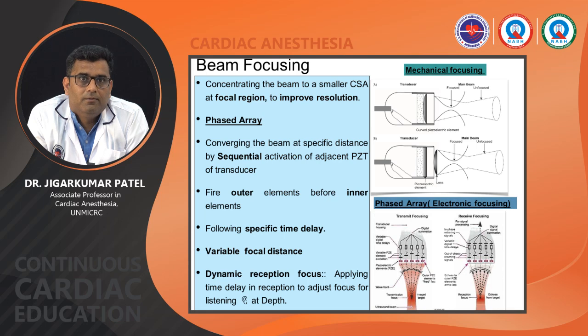And this focusing method is used not only during transmission, but also in reception. It is known as dynamic reception focus. So they apply time delay in reception to adjust focus for listening at depth.